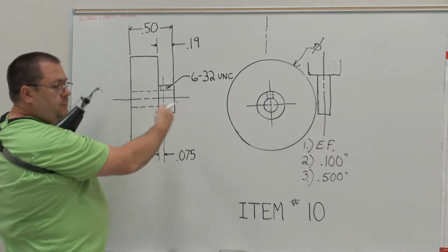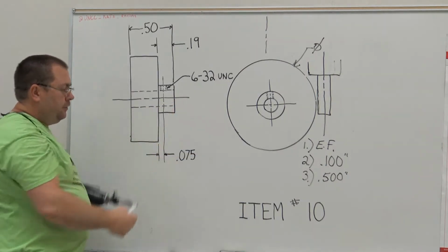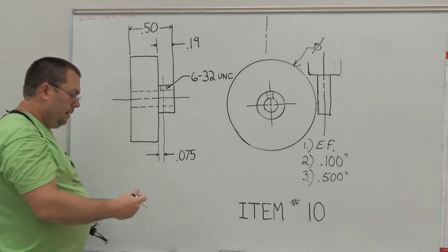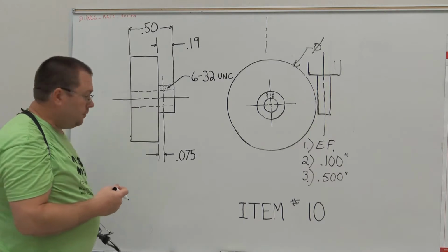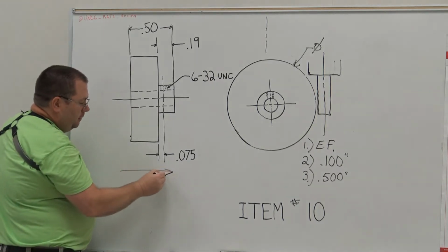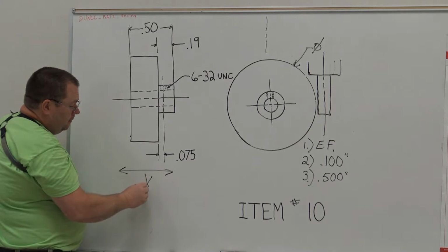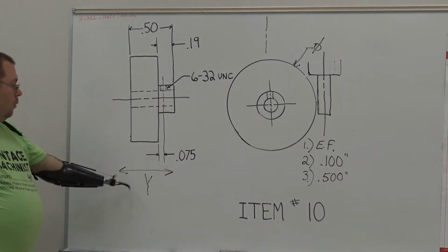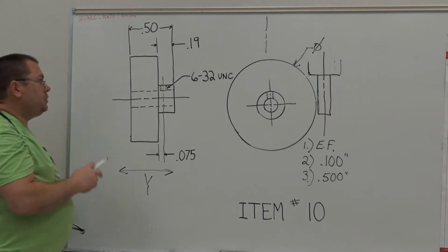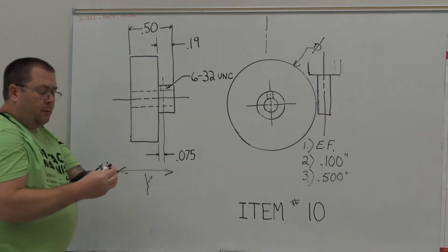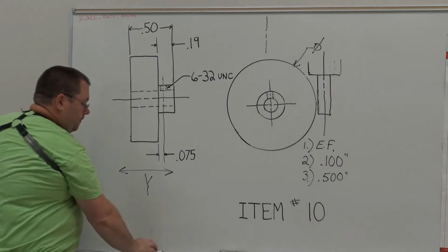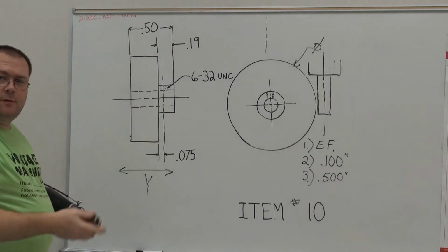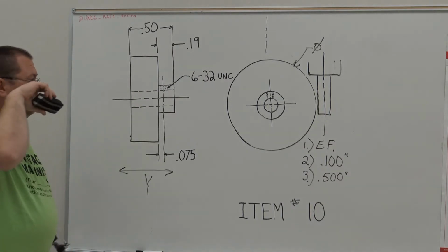So now we're going to turn over to our side. This is the side view. So if I stand beside the machine, looking at the profile of the part, I'm going to be moving in the y-axis direction. So in this component, we're looking at the y-axis and not the x, okay? So my y-axis here, I want to edge find, and quickly what I'll do is I'm going to remove these here in a second, just so that it's more clear where we're edge finding from.